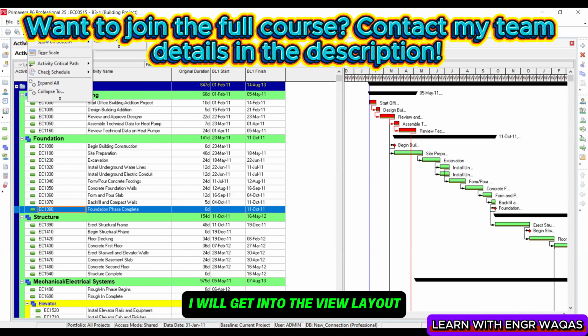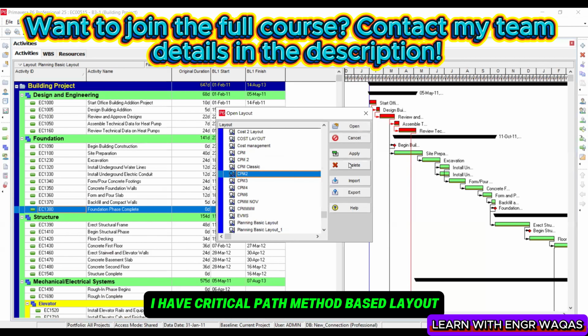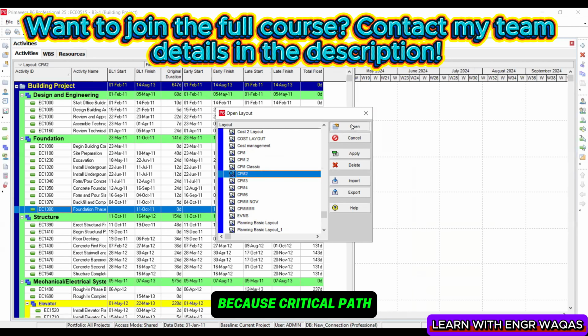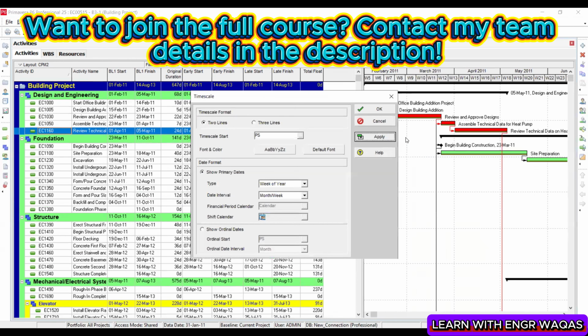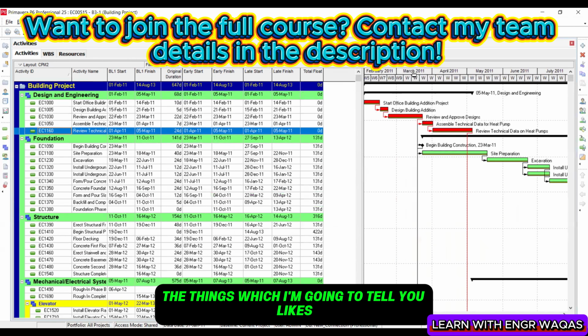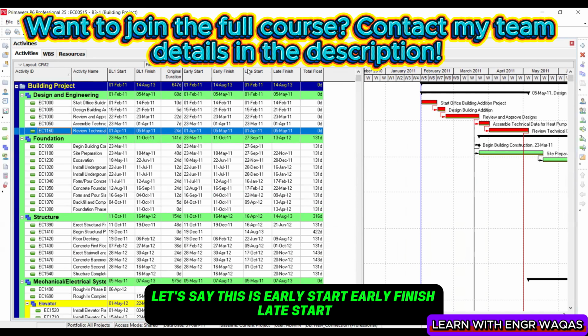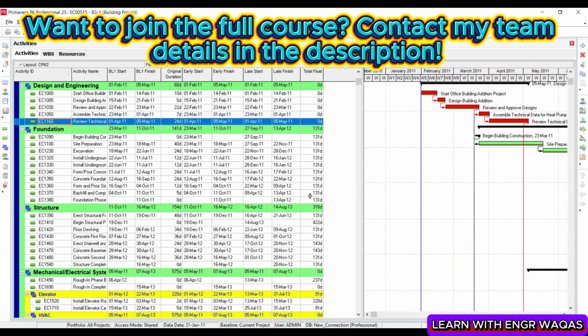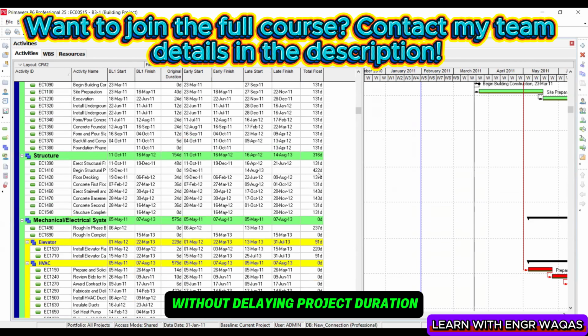I will get into the view, layout, open layout, because their layouts are going to help me a lot. I have a critical path method based layout, because critical path method is going to tell you about the things which I'm going to tell you, like you can see over here. Let's say this is early start, early finish, late start, late finish, and total float. Total float is the amount of time an activity can be delayed without delaying project duration.